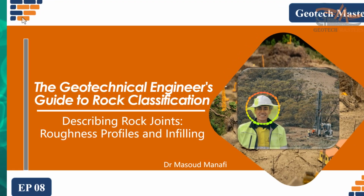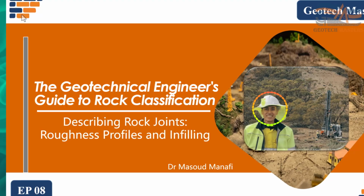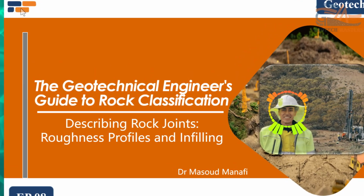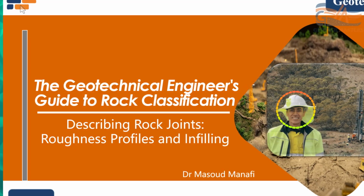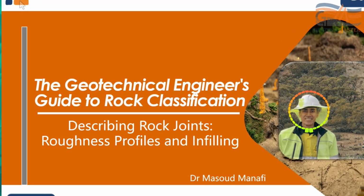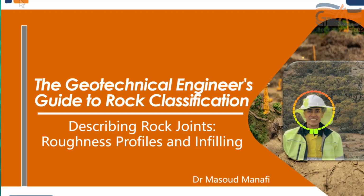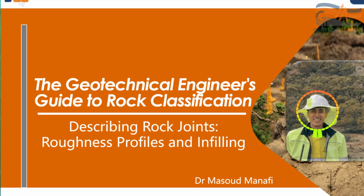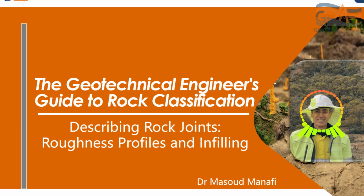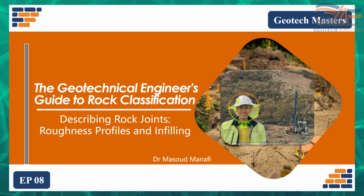Why does this matter? Because a rough, tight joint is very strong, but a smooth, clay-filled joint is like a greased slide. Understanding these details, roughness, aperture, infilling, and seepage, is the key to predict if a rock slope will stand up or slide down. Let's get to work.